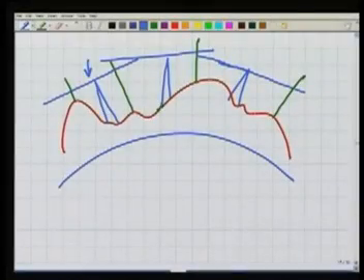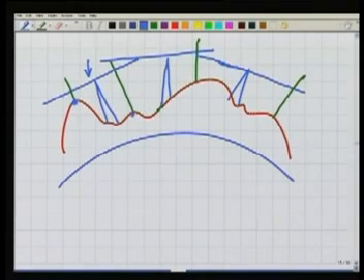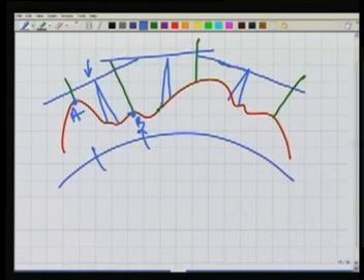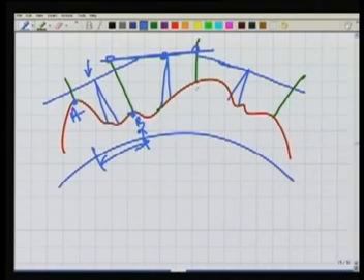Well, the very first time here, we have a horizontal line of sight. We determine the difference in elevation between points A and B in a very small area. For a small area, we can consider that the datum, which is the geoid or MSL, and the horizontal surface or horizontal line are nearly the same. Then we establish another horizontal line here, and then we take again the observations RA, RB, so that we know the elevation of this point C. Then again we go to this, again we establish a horizontal line of sight.